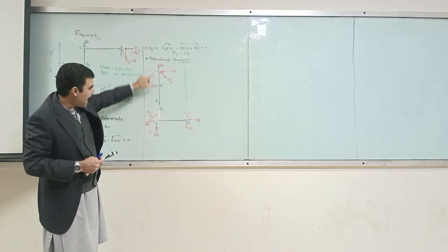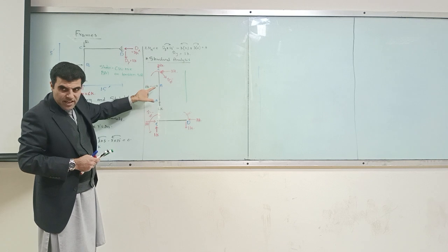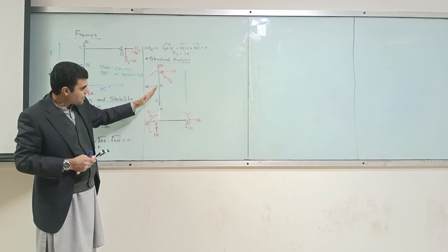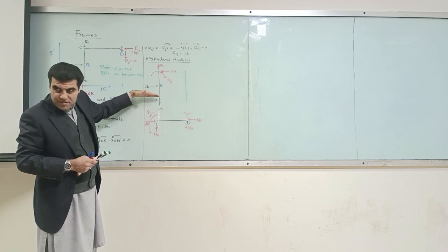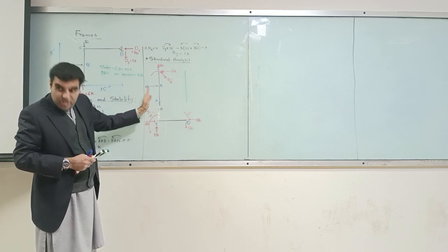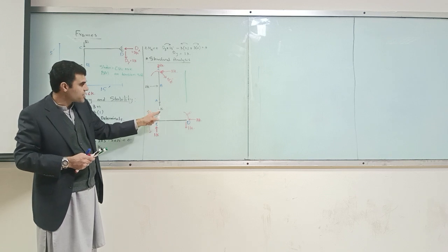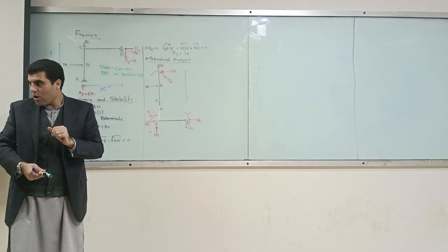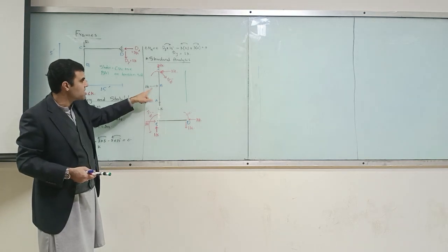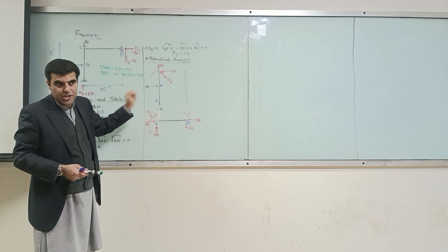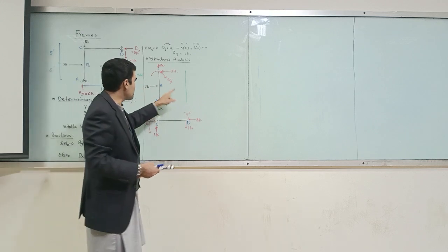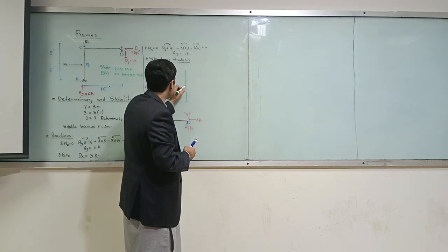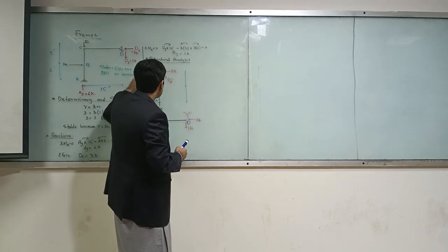In other words, I have got this structural component AC, and the applied load should be either perpendicular or have some inclination, not zero. The load which is 6 kip is not causing any shear force, that is just causing compression. So this is the only load which is causing shear force. So my shear force from A to B will be 0.